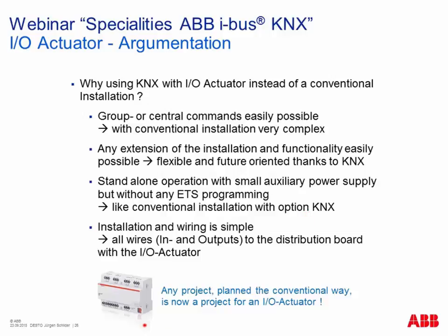And wiring is simple, in principle only all inputs to this device, all outputs, and then you already have a basic KNX solution with internal connections between inputs and outputs, and with the option to create some more functions like grouping, or together with other devices some more functionality. So not in every project necessary, but we have some nice projects with this solution, and you see it's a kind of niche product, but makes sense sometimes.